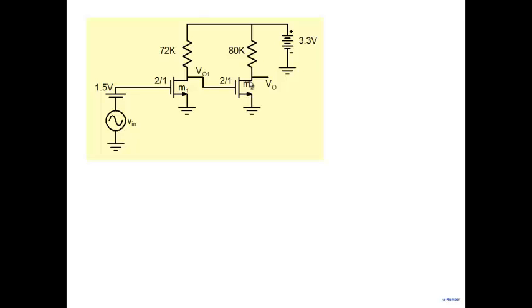How do you find the frequency response? Frequency response will not be determined by the second stage or the first stage alone. How do you determine that? Well, our approach is the open circuit time constant approach, which means that for each capacitor, find out the resistance that it sees and sum up the time constants. So what you do is the following here. This is our approach. So you say time constants are here.